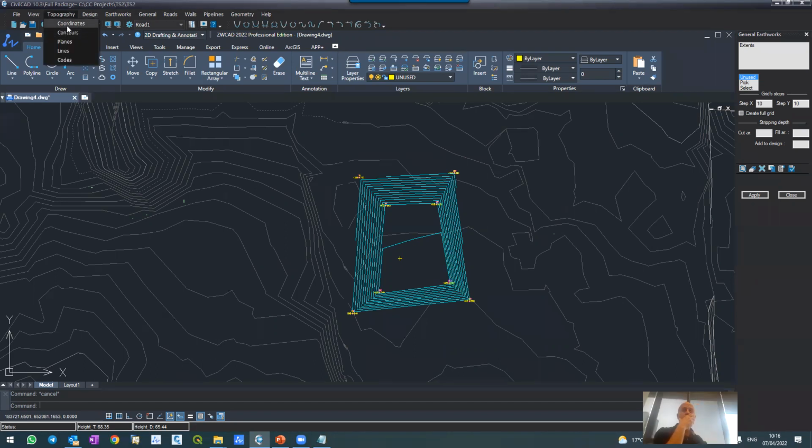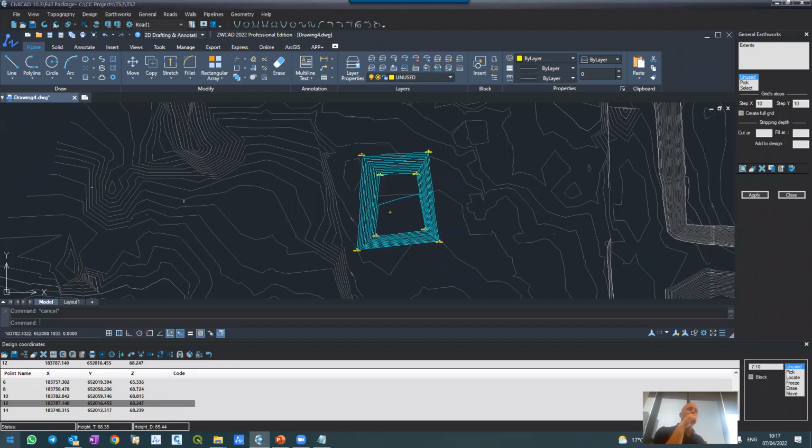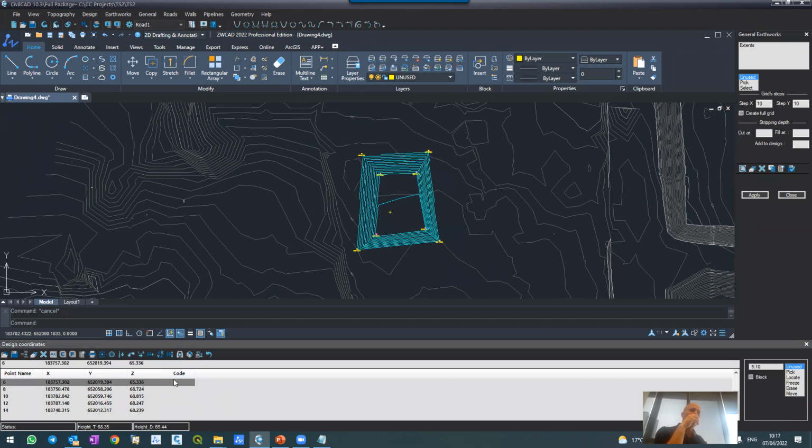And one more question. Is it possible, by code with some syntax, to measure and import break lines from the field? For example, can I code the line beginning of an arc and the end of an arc, and when I import data, get break lines to the surface straight from the survey data? Yes. So the answer for both is yes. In fact, if you go here, you see there is another column. We call it code. You see?